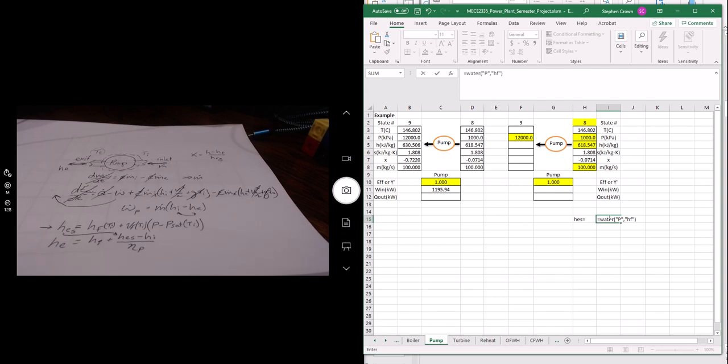And actually I can do that at the temperature. It'll work either way, but it makes more sense to use the temperature, since that's how I have it written. HF at, and then the temperature. So I'm going to use this temperature because later this temperature will equal a different value. So use this one, which is really the exit temperature if it's isentropic.